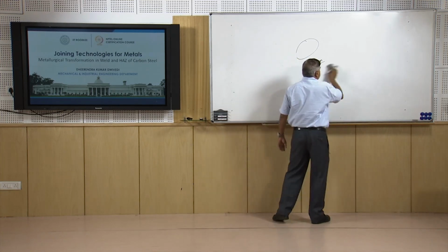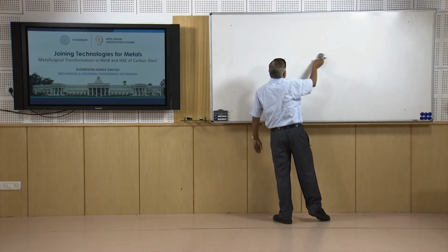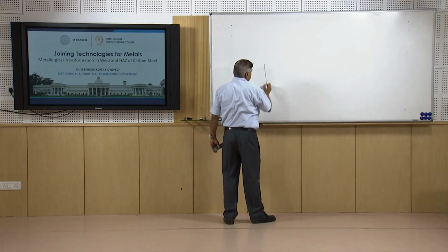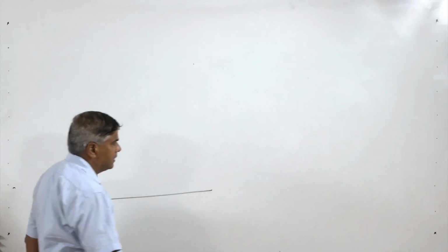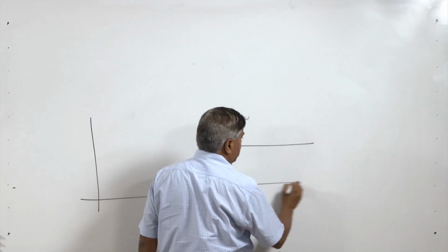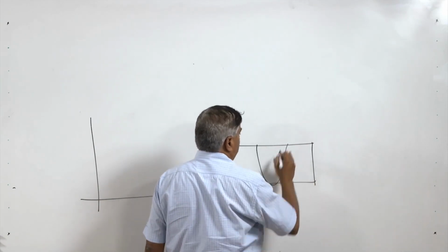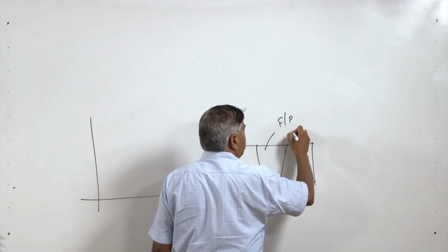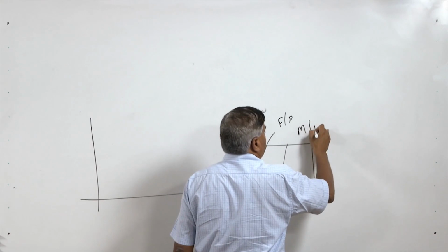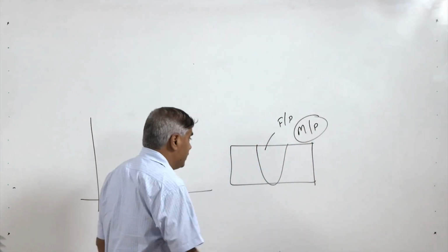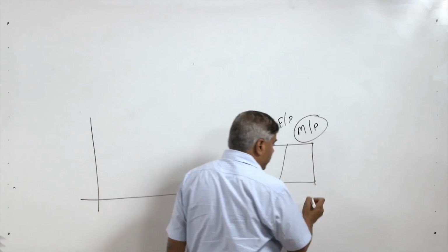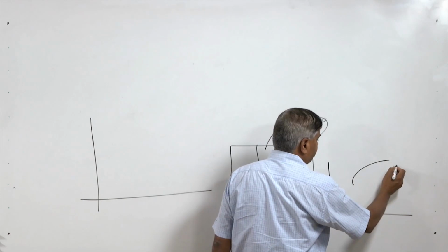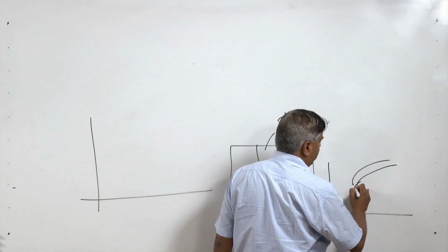In the heat affected zone. So far we have not talked about the weld. In general, the weld experiences a much higher heating rate as well as cooling rate, and that is why, as per the carbon content in the steel, mostly it forms either ferrite or pearlite, or it may form martensite and pearlite in the weld, and that is what will be governed by the composition of the steel. So, for that we need to see the CCT diagram for that particular grade of steel.